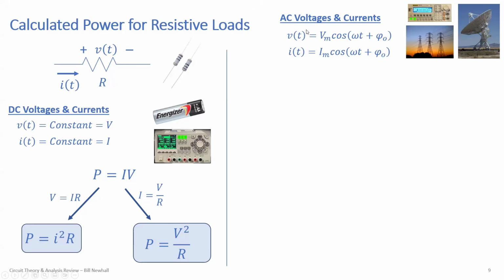When you apply an AC voltage across a resistor, the current is that voltage divided by the resistance, and resistance is a real value. It's not imaginary. So if we were using phasors, flashback to phasors, voltage and current would be in phase. The zero crossings of voltage and current would happen at the same point for a resistor because they're just proportional by the resistance.